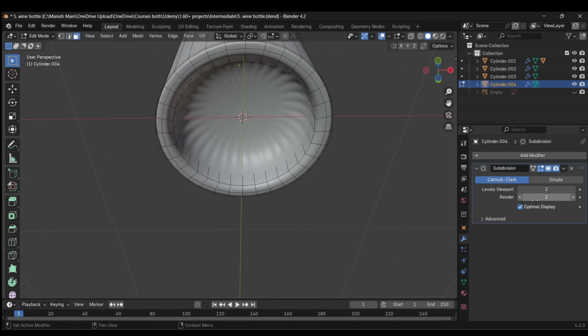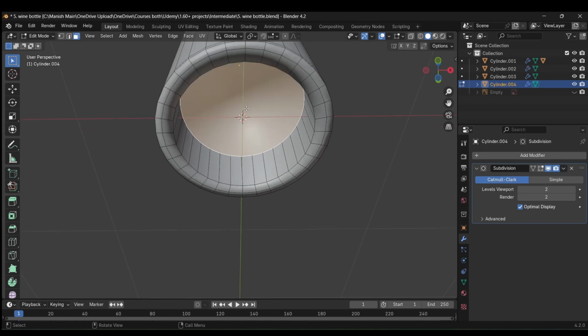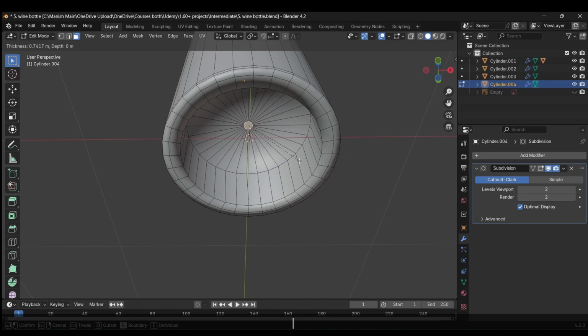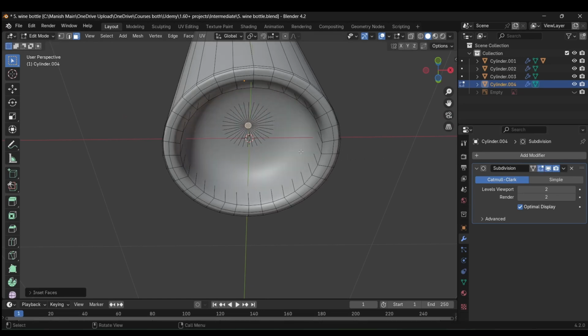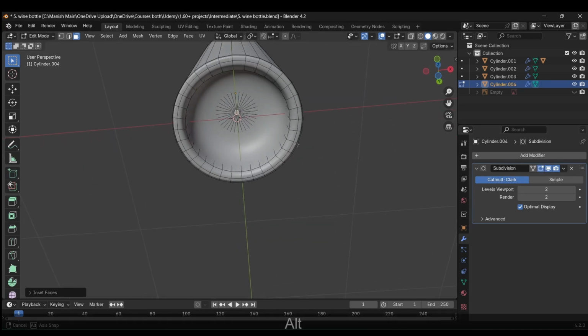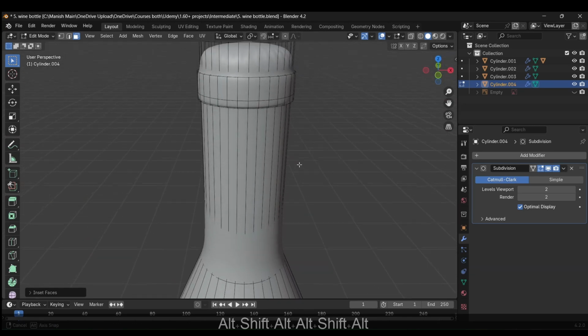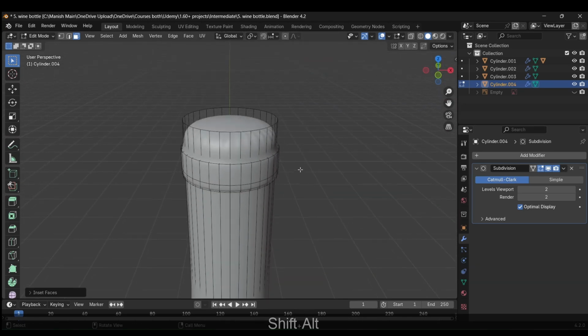So I'm gonna select this. For selecting this, I'm not able to select it. So if you press this toggle button, then the subdivision modifier is not active in the edit mode. So I'm gonna select this. Now the subdivision modifier is inactive in only the edit mode. So press I to solve the stretching issue and again enable the subdivision modifier. That's good. Now everything is looking good.